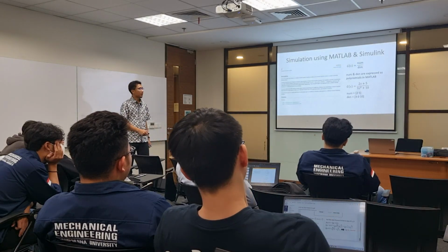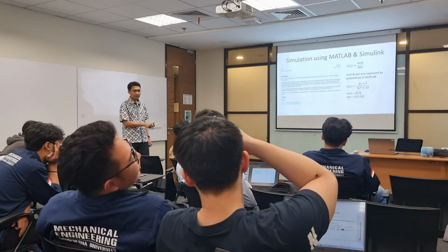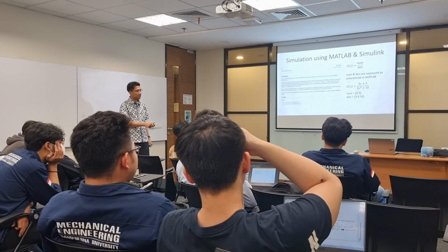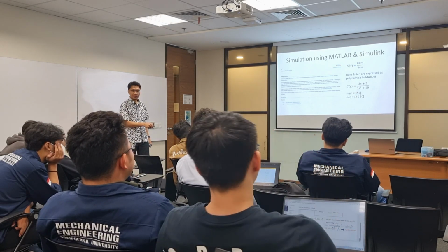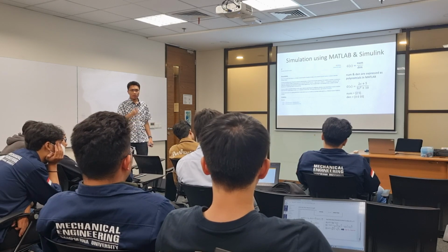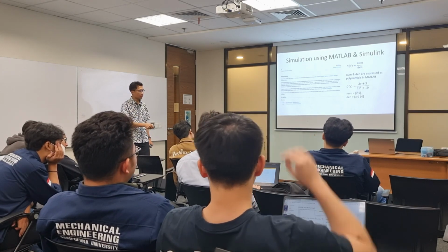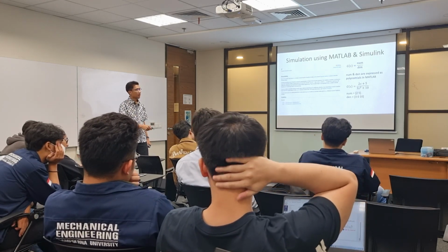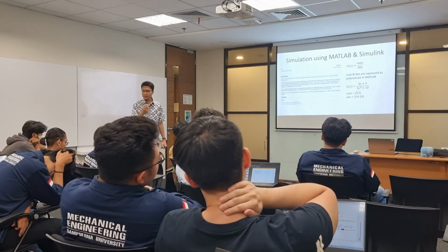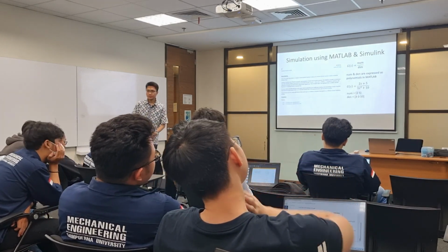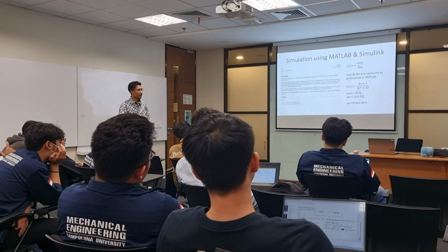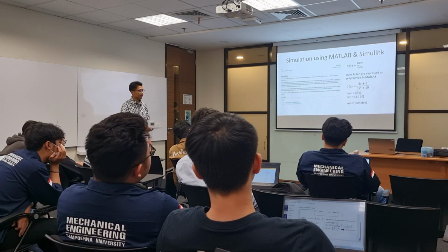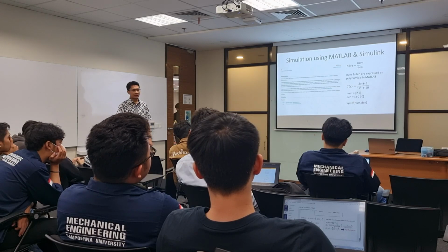Okay. And then what about the denominator? 3s squared, so the power 2 multiplied by 3. Do we have power 1? No, so we put 0. And then the power 0 is 10, so you put 10 on the third term over there. Okay. And so you just write sys = tf(num, den).